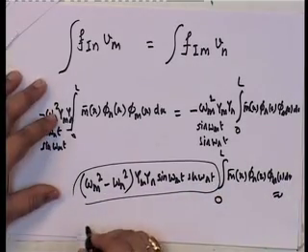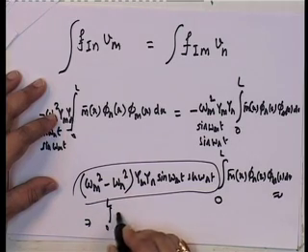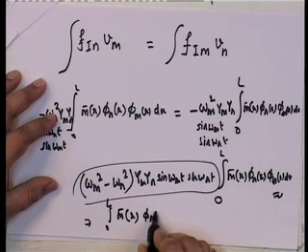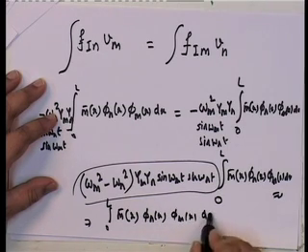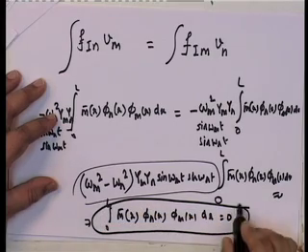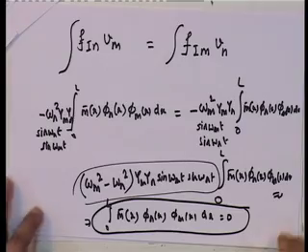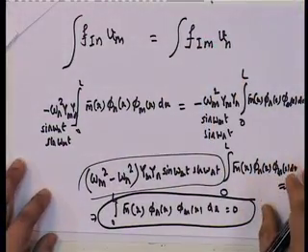These cannot be 0. Automatically this implies that the integral from 0 to L of m bar x phi nx phi mx dx equals 0. This is the mass orthogonality condition that we have. Okay. So this in essence is the orthogonality condition that I have derived. In the same way we can derive it for the other case, but it just gets a little bit more complex, and there is no need to. All I say is that we know that the mode shapes are orthogonal in this particular case.